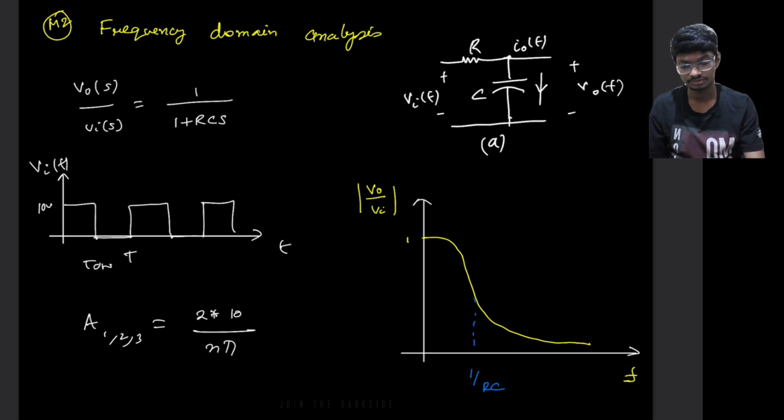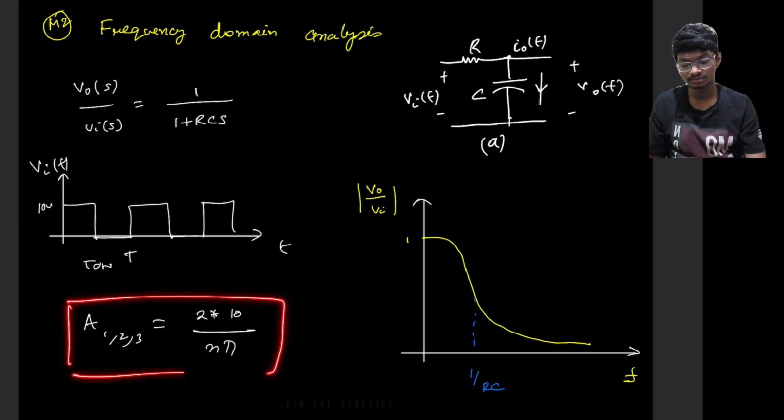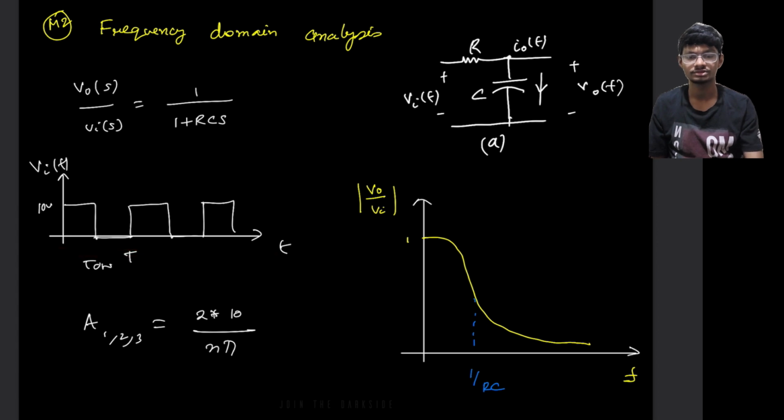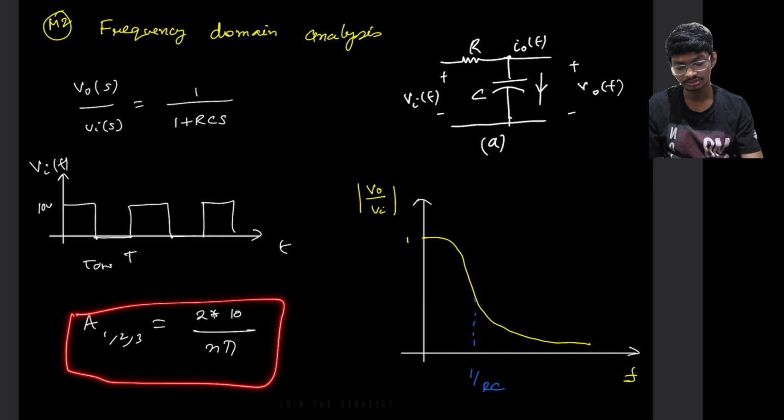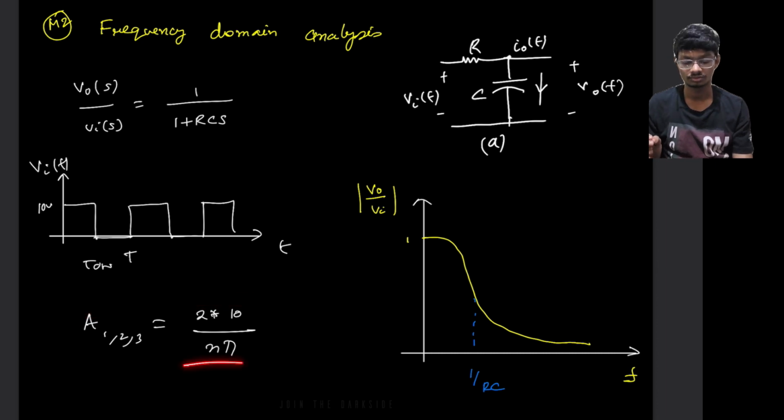So this is basically the coefficient. As you can see, it is inversely proportional to n. The greater the harmonic, the more the amplitude of the harmonics gets reduced. This comes from a derivation of a square pulse. If you put that in a Fourier series and solve, the result will come out like this.